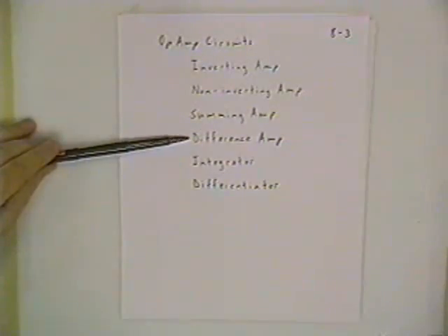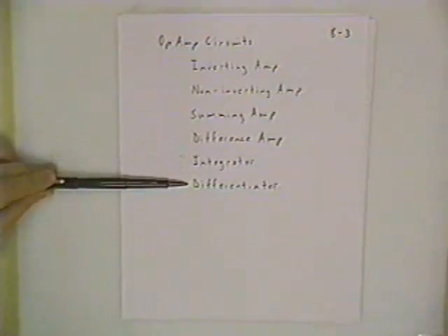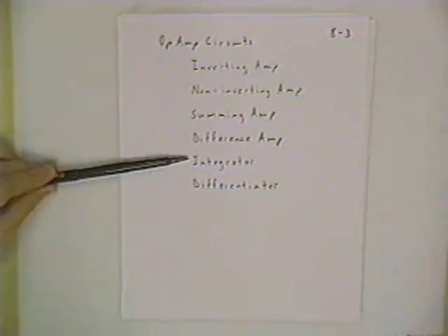It allows one of the inputs to be a set point for a thermostat, for instance, and the other input voltage is a measured voltage from a thermocouple. And so you can have the op-amp circuit creating an output voltage that's either positive or negative depending on whether the temperature is higher or lower than you want it to be. And that has very useful applications in instrumentation. For signal processing, sometimes we want to have the integral of the input signal or the derivative of the input signal, and that's where these circuits called integrator and differentiator come in.